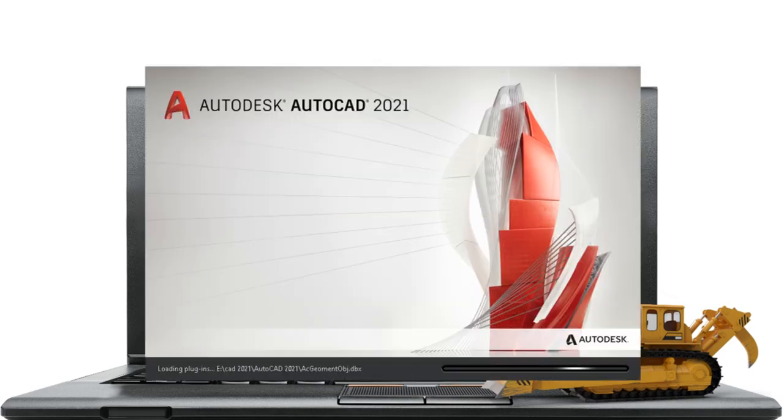In this session, we will learn about how to use layers. Layers are like a group of transparent sheets that are combined into a complete drawing. For example, the object lines are created on the object layer and dimensions are created on the layer called dimension. You can easily turn off dimension layers for a clear view of the object lines. So, in this session, we will learn how to create and delete different types of layers.